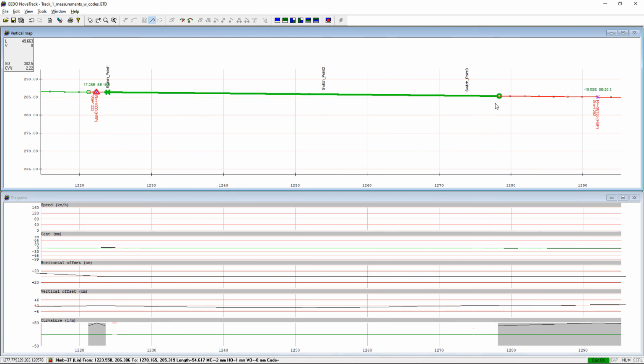And then we have to adjust the straight element at switch point 3. So we move the end control point of the straight element exactly over switch point 3. So the radii element was extended, or basically it was moved, and we have here the vertical offset of 0.